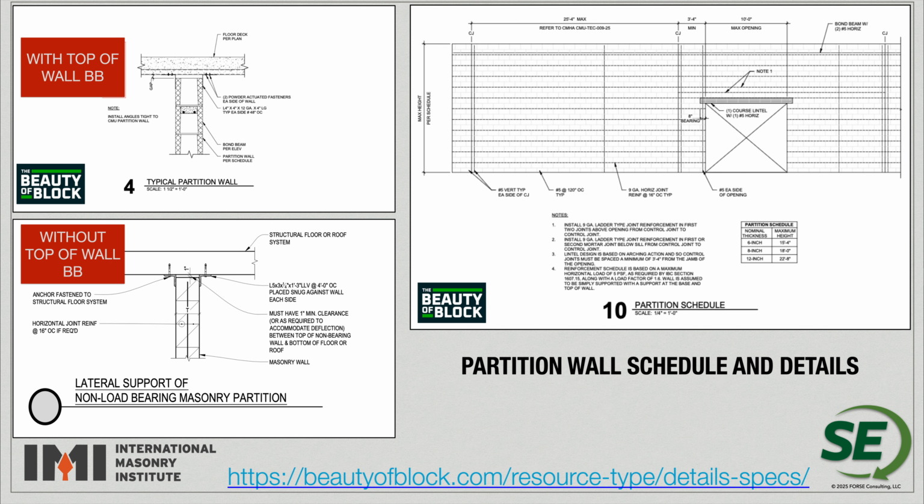Again, within the Block Design Collective, there are some standard details for connecting that top of wall. Here you can see a detail showing a bond beam near the top, or the detail on the bottom left showing horizontal joint reinforcement used at the top of the wall and no bond beam. But either way, we have a lot less reinforcement that we would be able to use because it is a partition wall.